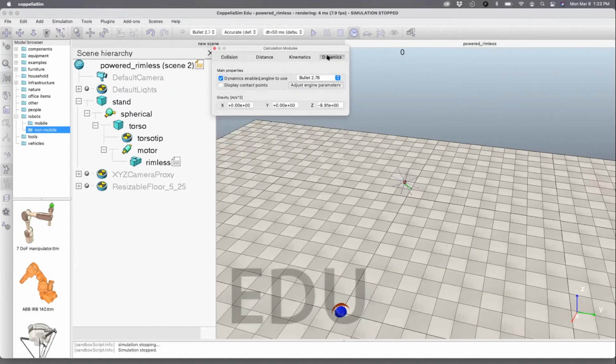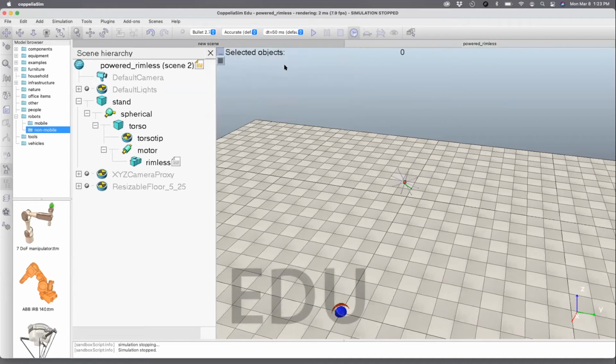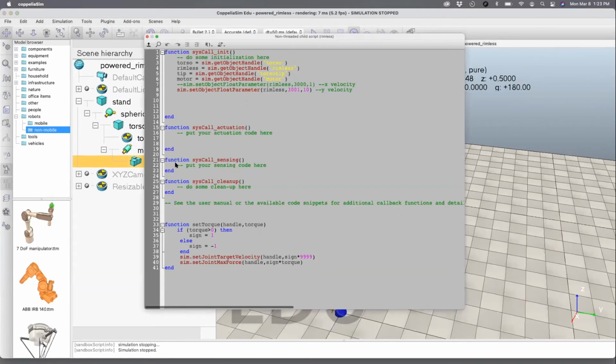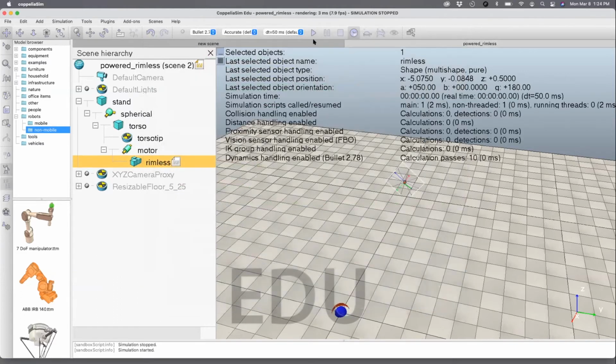There's something called dynamics. This is where you set the gravity. So let's just set it to 0. Okay, if you set it to 0, this is in free space. It's still moving, and that's because if you see this, I launched it with a certain speed of 10. Okay, so we can just kill that, just make it not move. So it's now not launched with the speed. Let's see what happens. So nothing is moving because clearly there's no gravity.